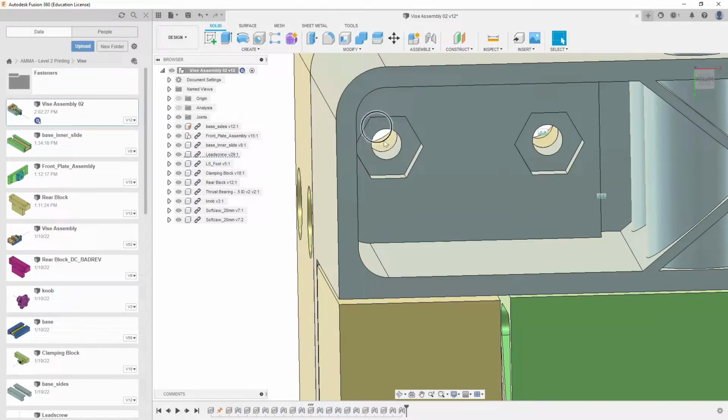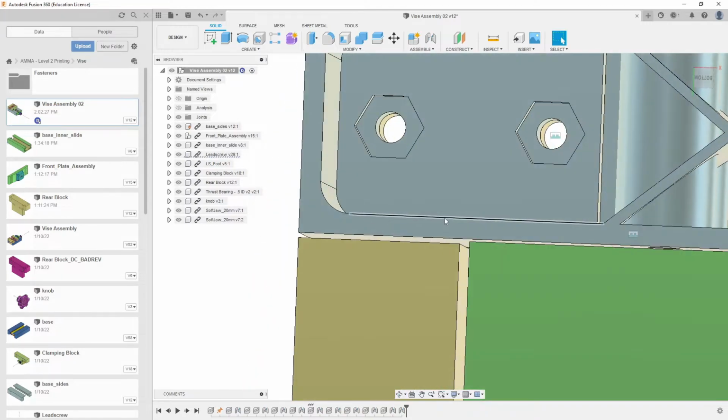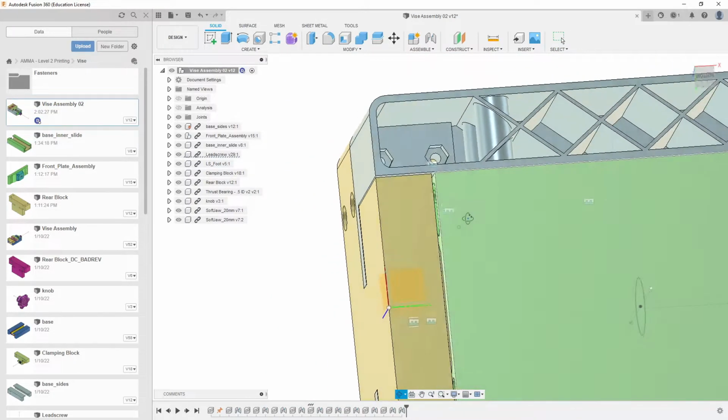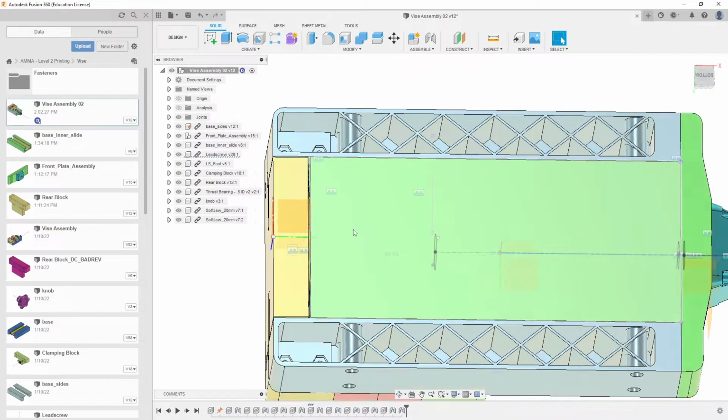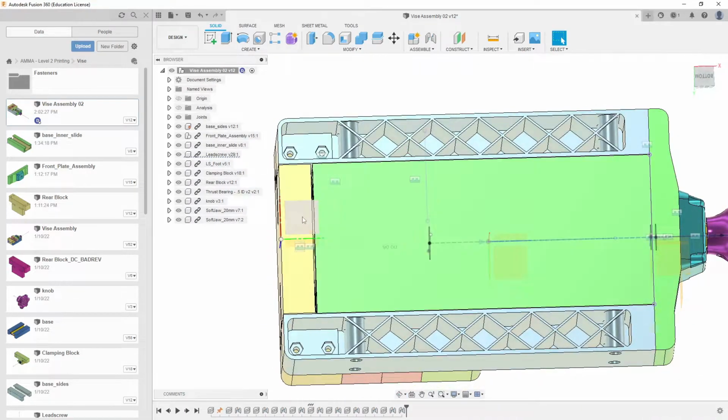So if the fastener has a lot of side load on it, it's going to be sticking out here kind of at an angle, and you're not going to get this fastener in here very well, the nut. Okay, so extra problems. So that's why we're leaving this bit of a gap. And I guess, which side did I want to put the gap on?